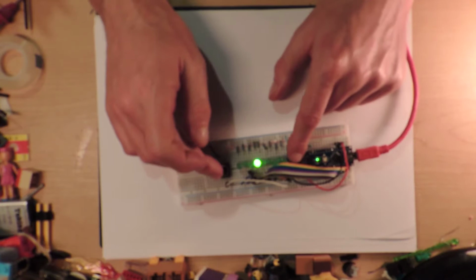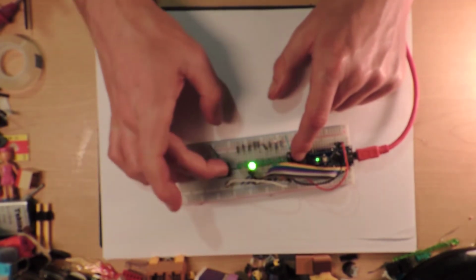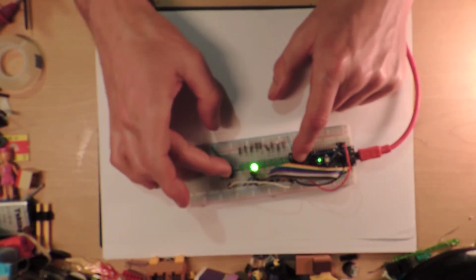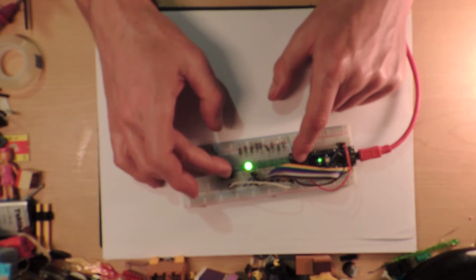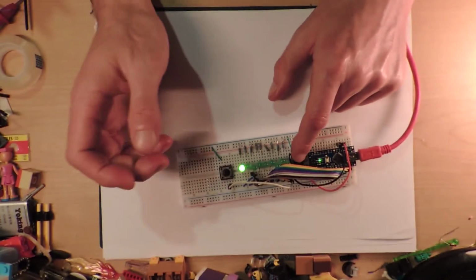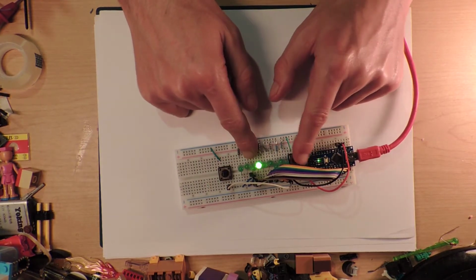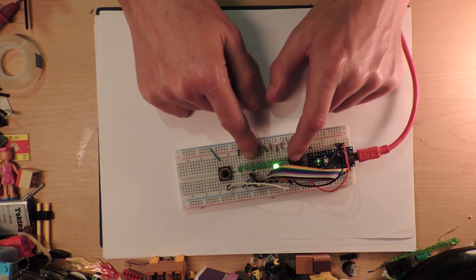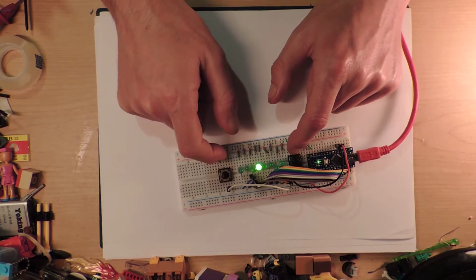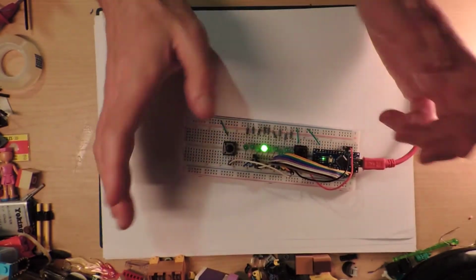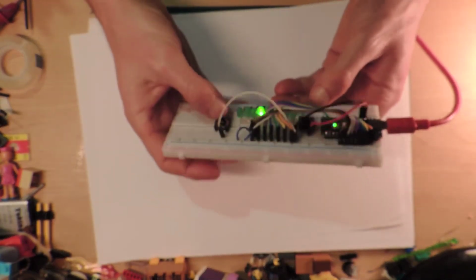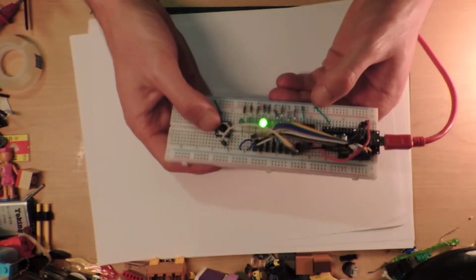But we're going to talk about this in a minute. Hopefully what should happen is I press once and it moves once. I press again and it moves. I press again and it moves. I press again and it moves. But you see it double jumps sometimes, so it's not exactly perfect. But that's okay. The problem here, I believe, is because there's button bounce.